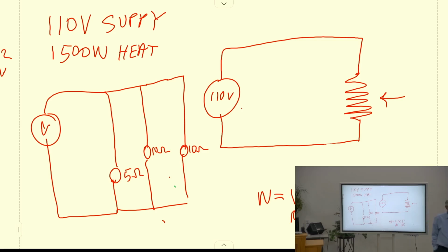And that's going right back to the line. Now you're supposed to have a transfer switch that opens the system. These guys, like in Florida, would get nailed. Well, hey, it's down, and it's coming from the other direction, from somebody's generator, not from the generation stations.